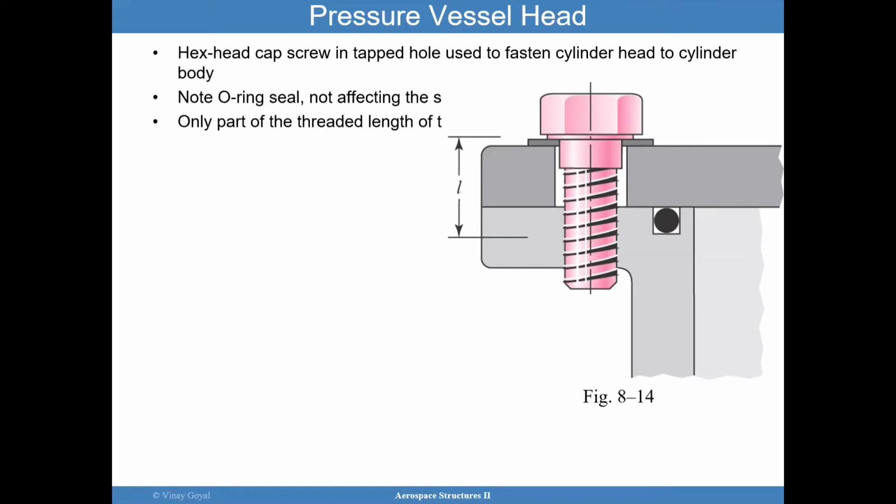that when thermal conditions are applied, the O-ring does not shrink too much or become ineffective, such as the case of the Challenger, where the O-ring was not effective. We want to make sure that if you have primary and secondary O-rings and a design problem, you understand that the design problem that occurred on the primary O-ring will also apply to the secondary O-ring.